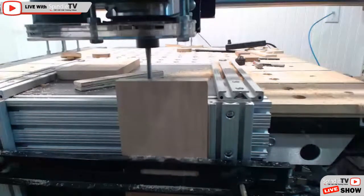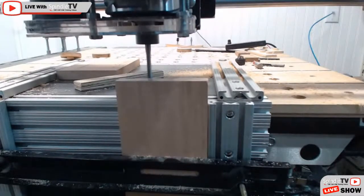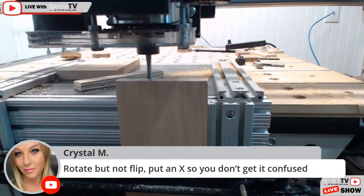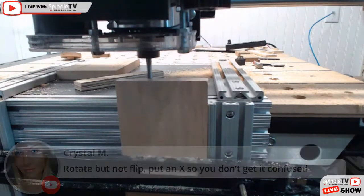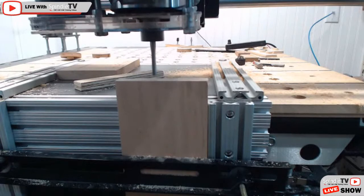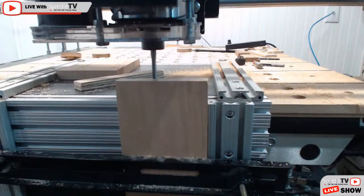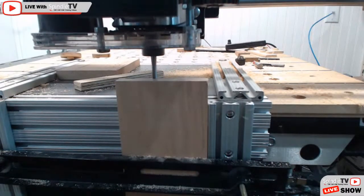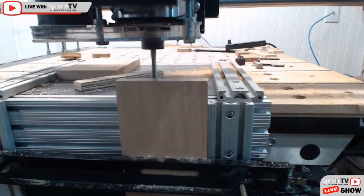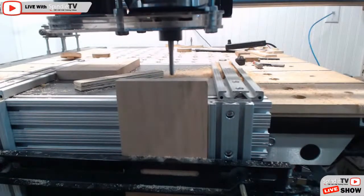Rotate, not flip. Very useful. Put an X so you don't get confused. That's a good tip. So you rotate your board. You don't flip it. You rotate it. Very good. Troy's answering some questions. You absolutely want to rotate, not flip, because that would screw your pin board up big time. Might not be too big of a deal on the tail board, but the pin board would be for sure. But you want to rotate, not flip.